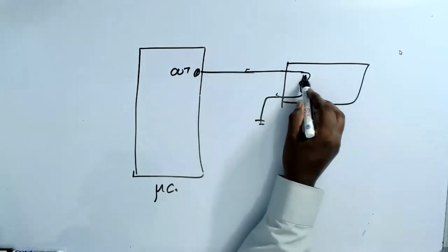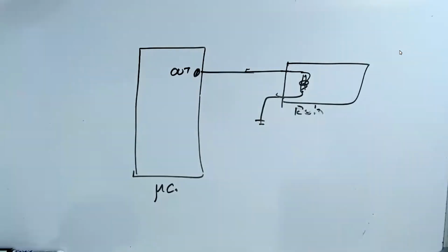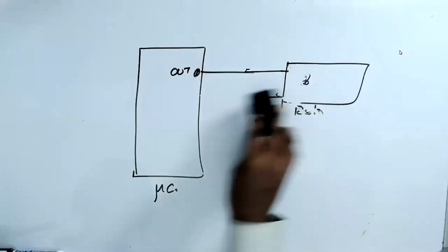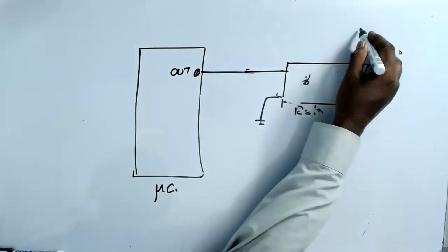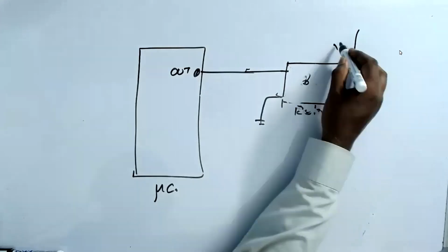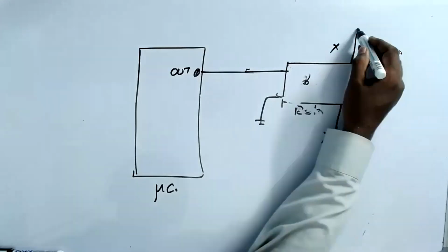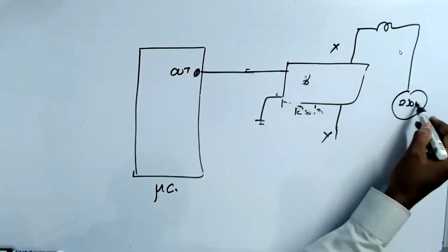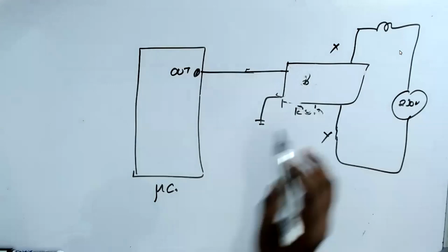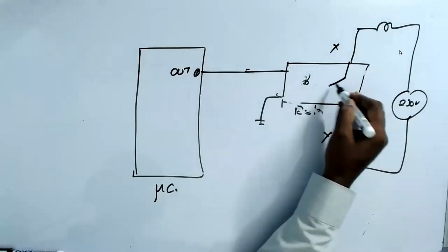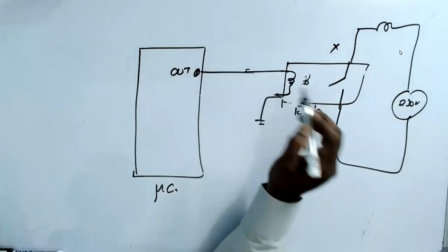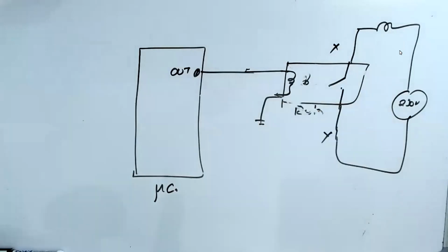Okay, now we have, it controls the two inputs as we already discussed. This is the input and output. And here you connect a bulb, 230 volt supply. Let us assume this is a switch. Now this coil controls the switch. So you can easily connect now any device, any AC, everything can be connected.